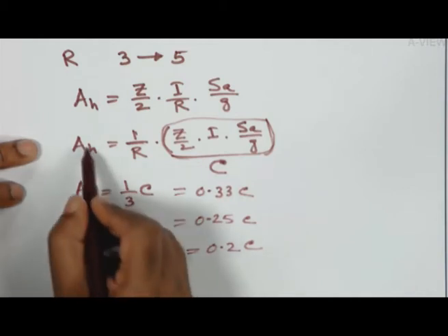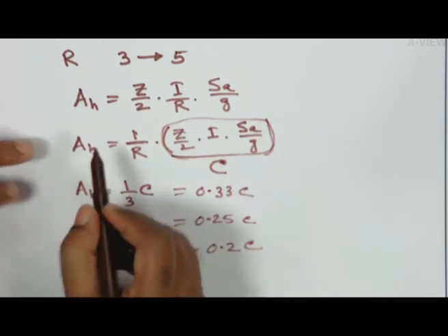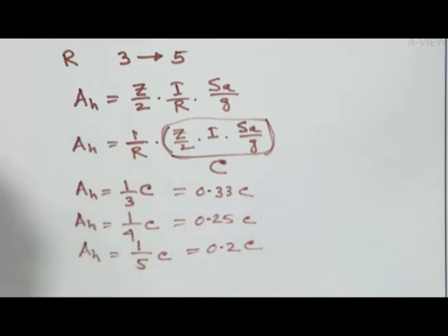That means this will be more. Whereas if I consider the special moment resisting frame, it will be 5. So this one will be again less. So that means how we are constructing that one, on the basis of that, how the joints are there, how far that is moment resisting, whether the proper development lengths of the steel are given. On the basis of that, you can decide whether you will go for 3.